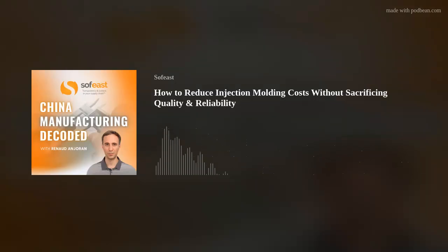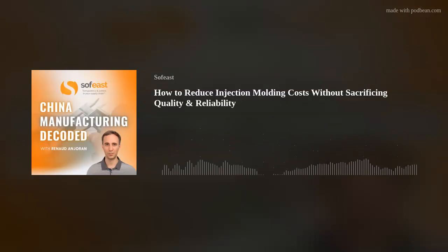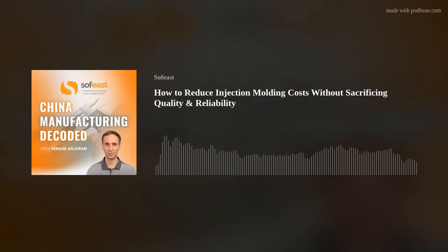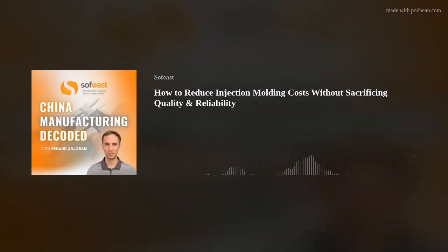The tool molder is going to take into consideration the scrap rate and therefore increase the unit price, as well as the tooling price going up, because he knows he's going to have problematic issues getting the part out of the tool itself. It's not going to run as smooth. So all of these things we need to look at, taking into consideration best practices, in order to get that part out of a really well designed tool.